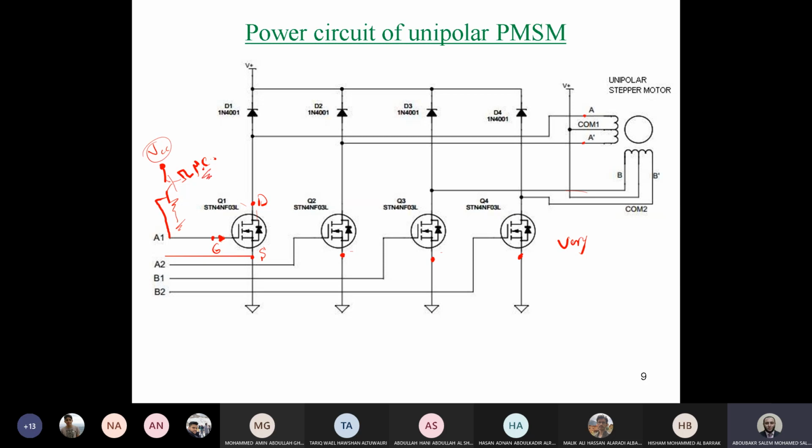Not from the microcontroller. And as we said, in this case, you will need a transistor for each MOSFET, for each power switch, okay, with a common supply. You don't need a separate supply or separate grounds, because as we said, the ground or sources are common for this circuit. Is it clear guys?